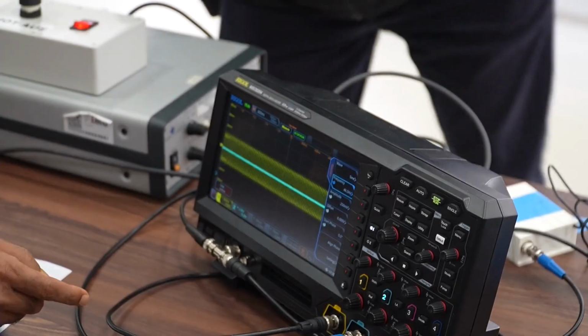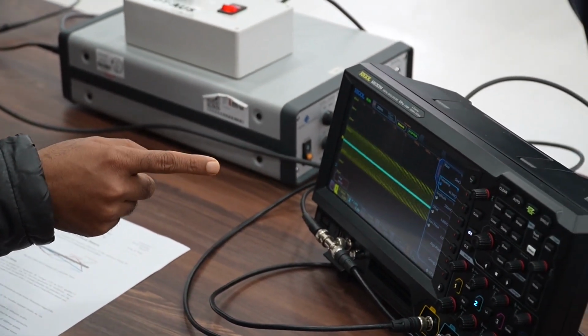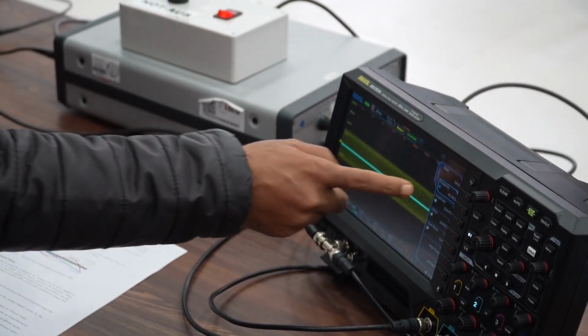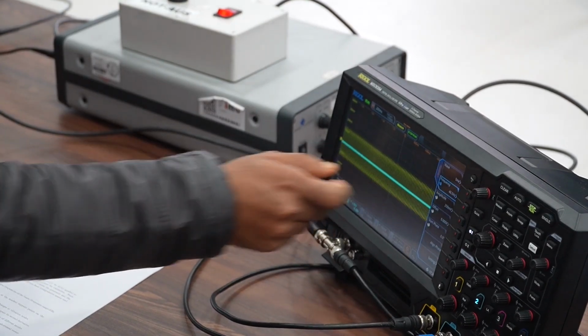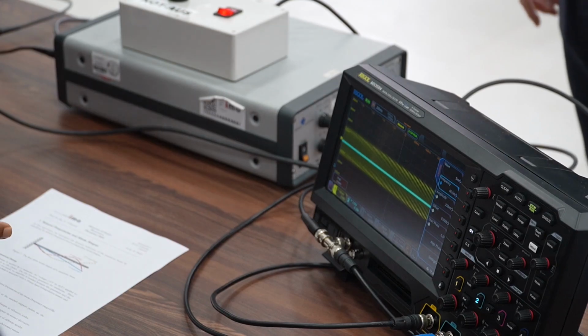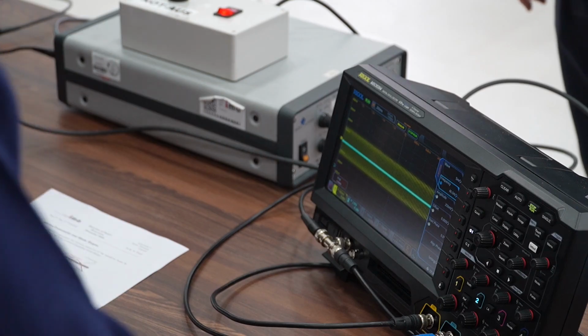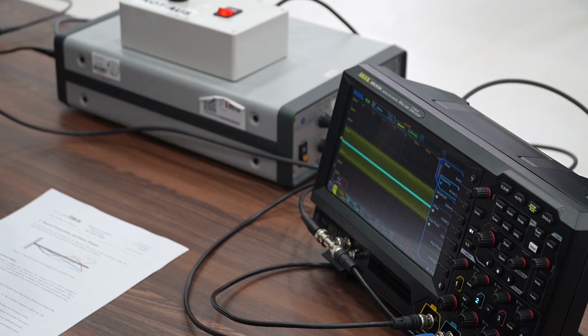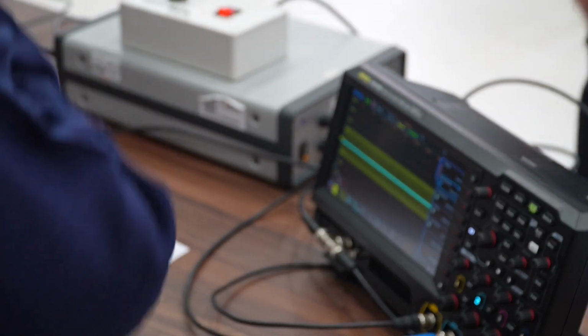Okay, and now what is the frequency? 46.5 Hz. Where do you want to start? With what frequency you want to start to measure the first eigenfrequency? You should start below and then slightly increase it until you see movement. It is 46.5 something hertz. So we measured the first eigenfrequency, right? Yeah, so about 7. So you should start below 7. Somewhere below 7. Maybe you start with 6?